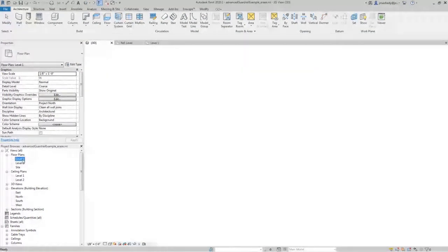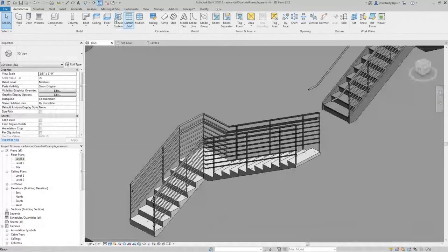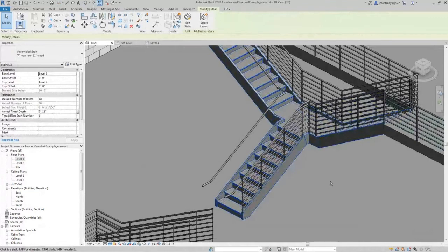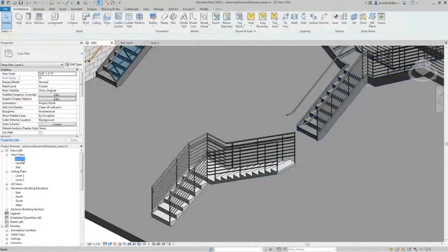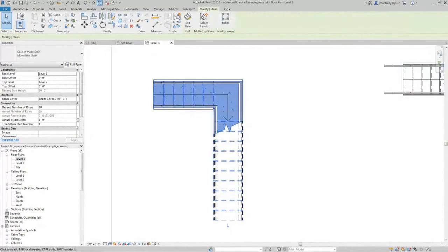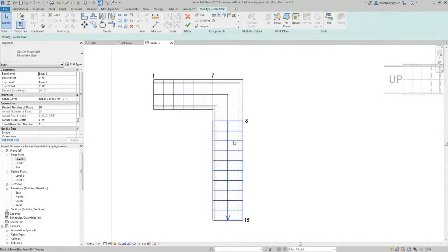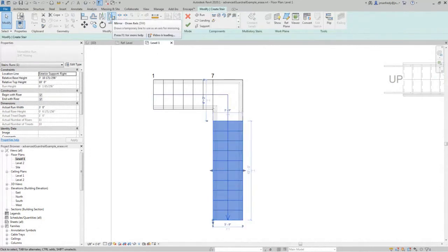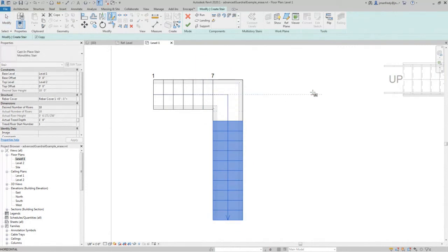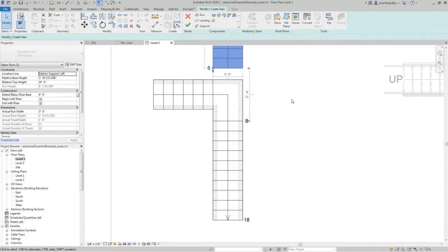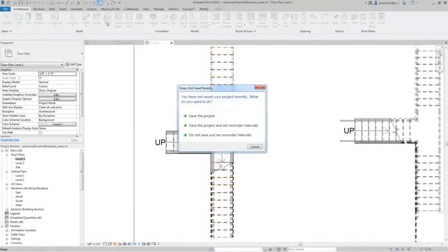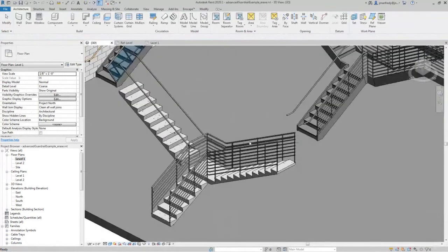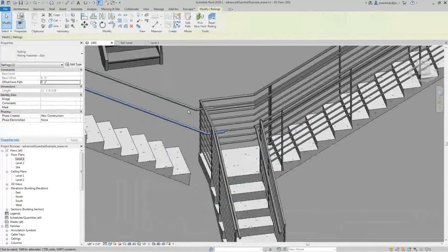But here you can also, Revit's going this way, and you've got a stair like this, but notice my stair goes in two directions. It's like a T. Well, how do you do that? Well, you can go into your stair and edit the stair. Take this half of the stair and duplicate it on a mirror line that you draw down the center of the stair somewhere. So somewhere in the middle here, draw a center line across, and it flips it to the other side. Now, if you just accept it like that, you're going to get some weird stuff happening because obviously it can't figure out the landing. You see, the landing is all kind of messed up there.